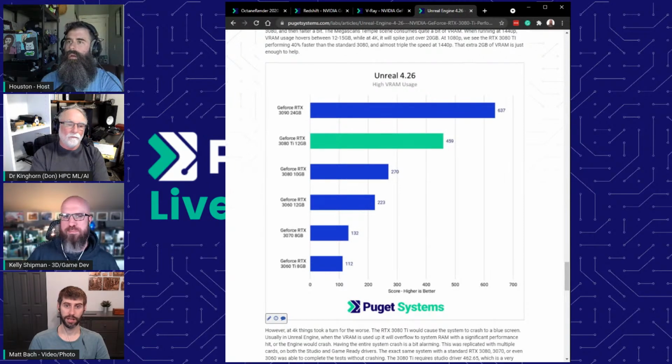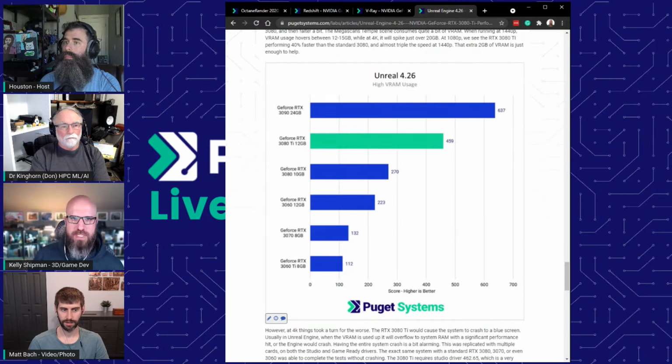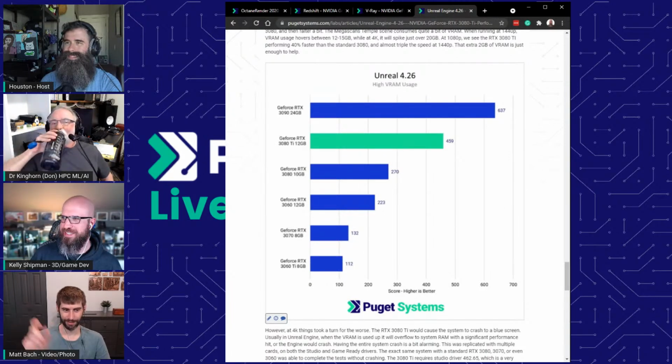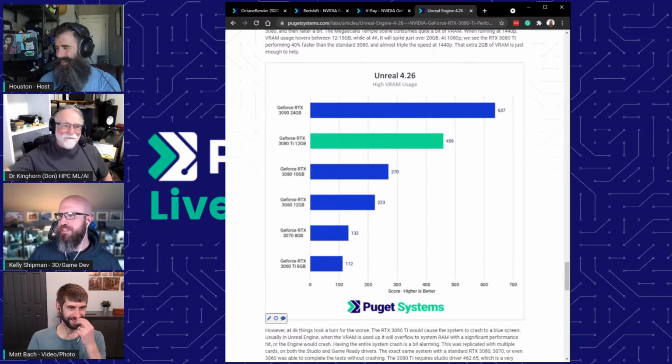So that's probably one of the situations where PCIe 4 is actually beneficial, because it's having to go across so much. Probably, I would imagine. That'd be an interesting thing to test. I could throw this on an older system and see what it does. You should be able to limit the PCIe gen in the BIOS. You can also use the sticky note method I've used for changing the number of lanes: count the electrical pins and cover them. It works, the X8 works.